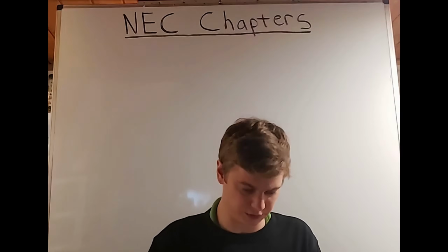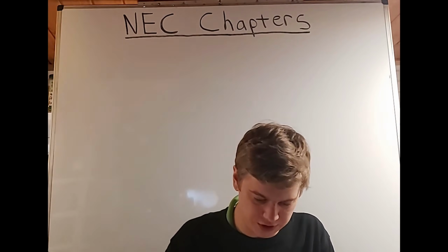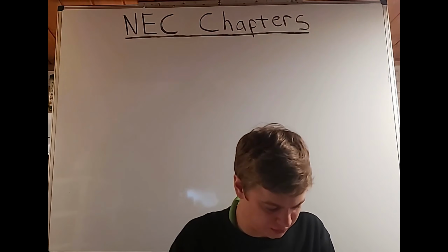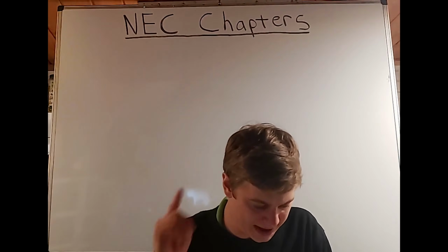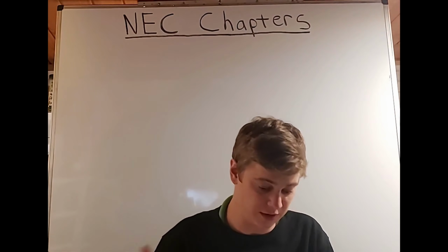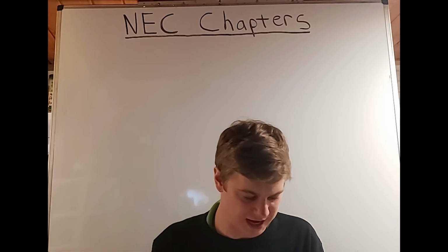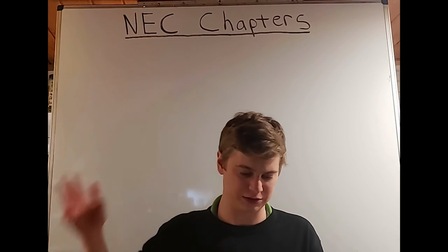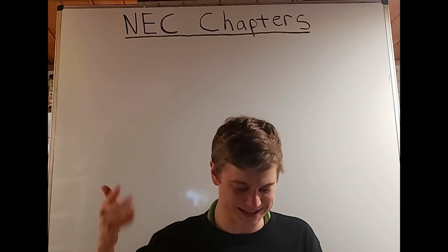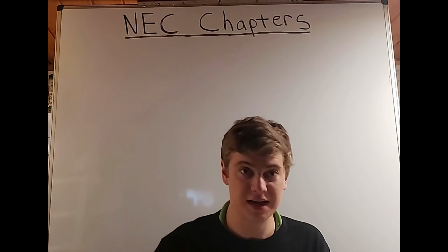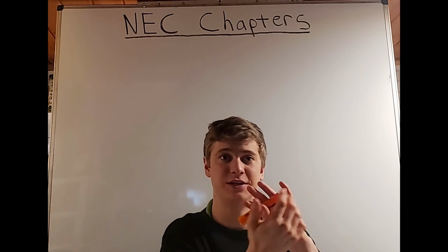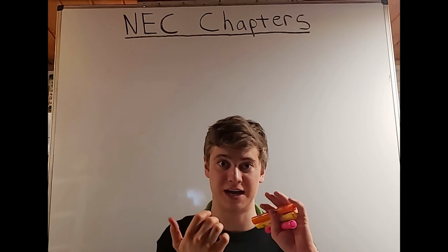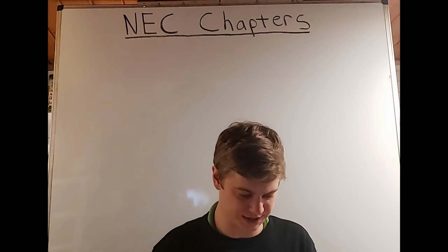A, dwelling unit. We see it mentions all the locations where you have to have a ground fault circuit interrupter in a dwelling unit. Okay, this includes 1, bathrooms, 2, garages, and also accessory buildings that have a floor located at or below grade level that is not intended as a habitable room. And then 3 is outdoors. Okay, so outdoor plugs, of course, you need the first one to have that GFCI, so they're all GFCI protected.